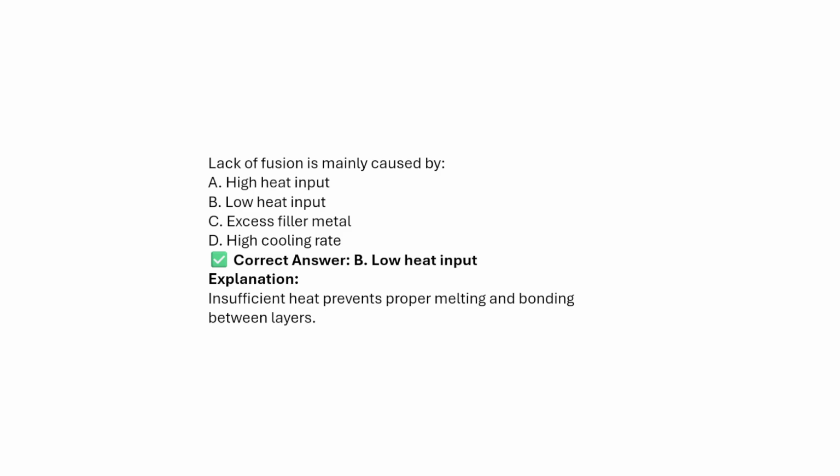Lack of fusion is mainly caused by high heat input, low heat input, excessive filler material, or high cooling rate. The answer will be low heat input. Insufficient heat prevents the proper melting and bonding between the layers.